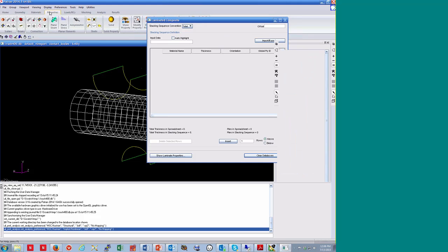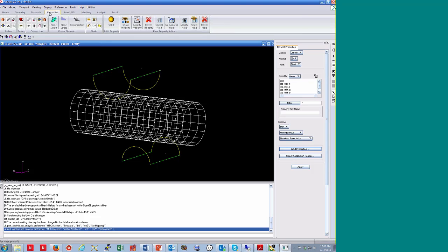Okay, then moving on to properties, you go to the properties tab here, and you can set up all your different 0D, 1D, 2D, or 3D properties. For instance, for 2Ds, you have your shells, bending, membrane, shear panels. 2D solid elements allow you to set up plane strain, plane stress, or axisymmetric, and 3D allows you to set up solid elements. They can be homogeneous, laminate, gasket elements. All of these are specific to Sol 400 now.